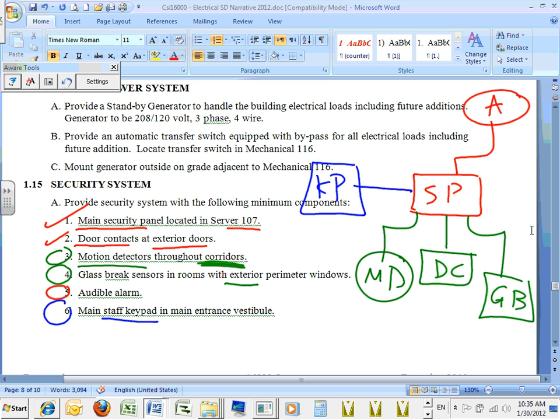This, what I drew right here, is called the security riser diagram. You will be required to draft this one for me, guys, as a riser, low voltage riser. How do we draft them? The low voltage risers, guys, drafting them, I'm requiring you to do it 2 ways. Either you do them in CAD and bring them to Revit, or you draft them directly in Revit. Draft. No views, nothing. We just literally draft what we're doing, and later on I'm going to ask you to put the size of all these cables between them and so forth. But for the time being, because that gets you into throwing your components, please do that.